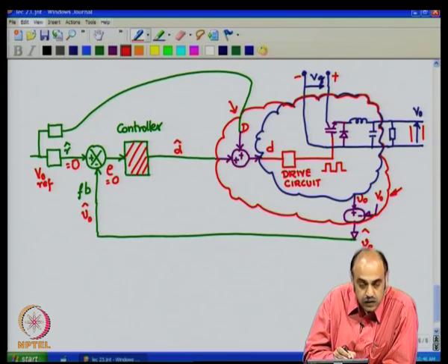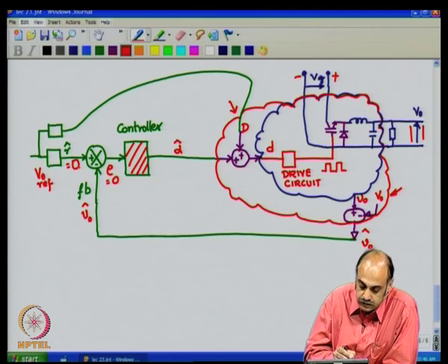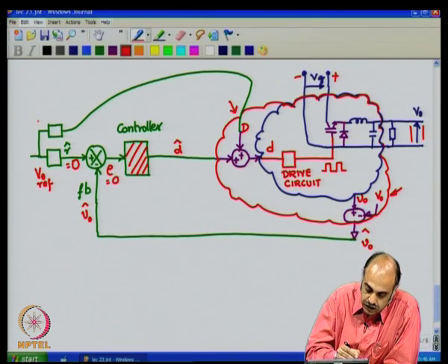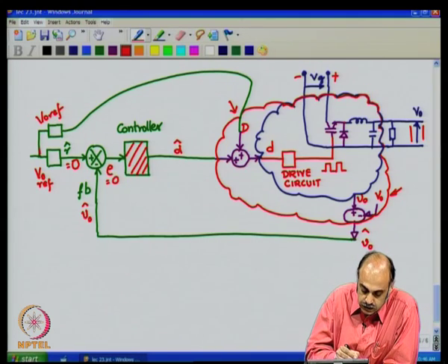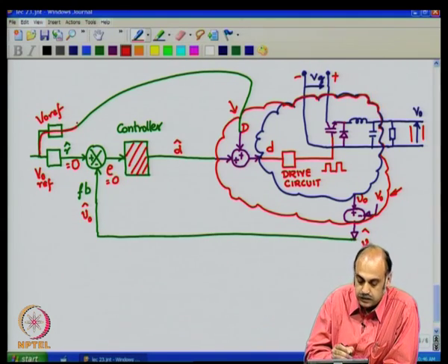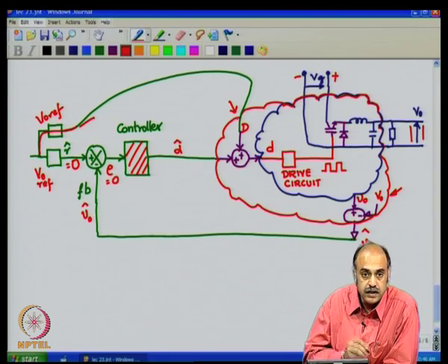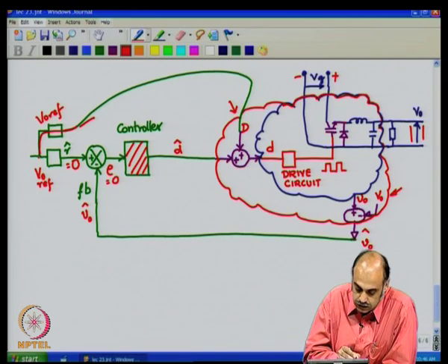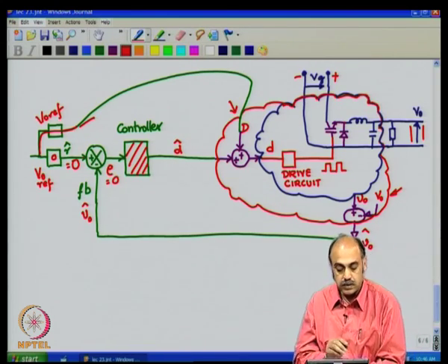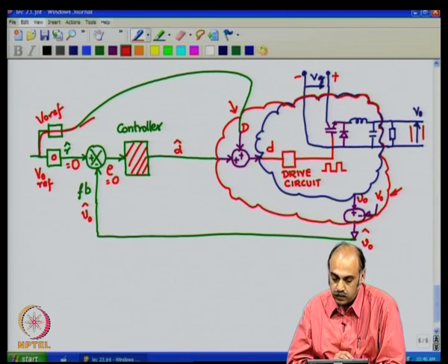The value is 0 for the R hat portion, and this would become V naught ref for the steady state portion. So, the steady state portion passes through like this and affects directly the D by a scalar here, and this gets multiplied by 0 to provide the 0 reference to the deviation portion. So, this will be how the controller setup will look like.